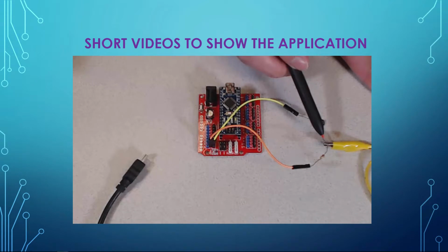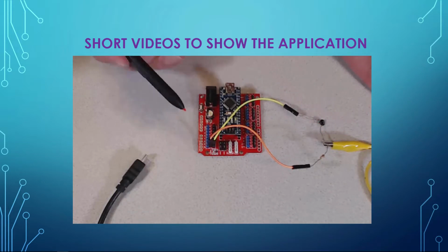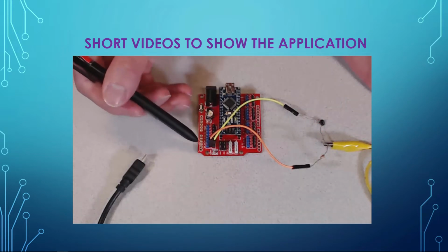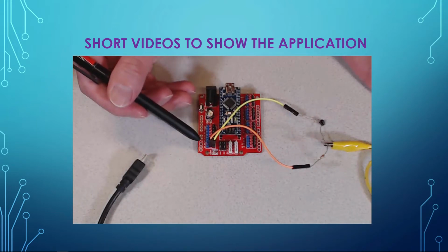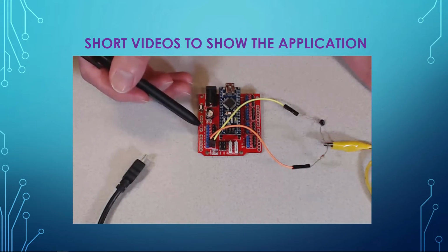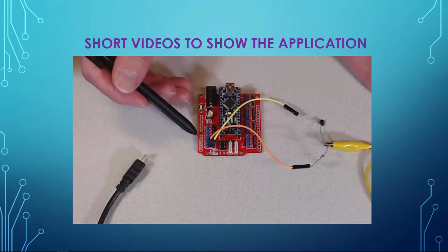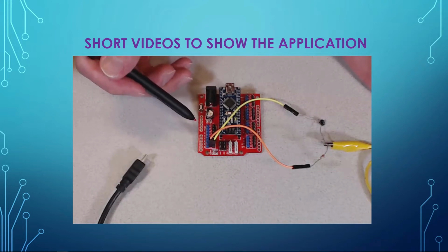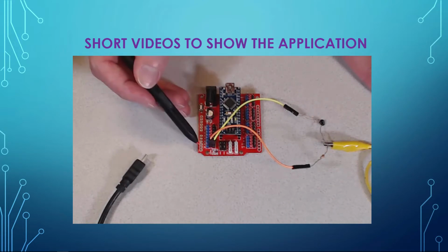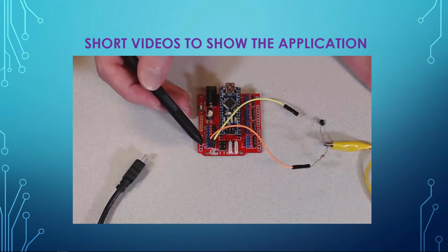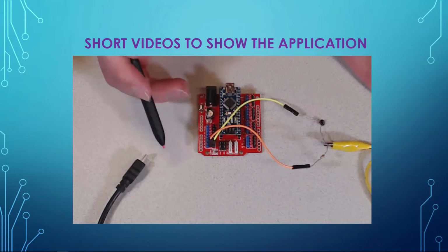To read the voltage output of the node here, we need to use the Arduino's analog read pin. They're over here. These pins are denoted with the letter A before the numbers. When you set the Arduino to read from, for example, this pin, it detects the voltage and returns a 10-bit value that needs to be processed.